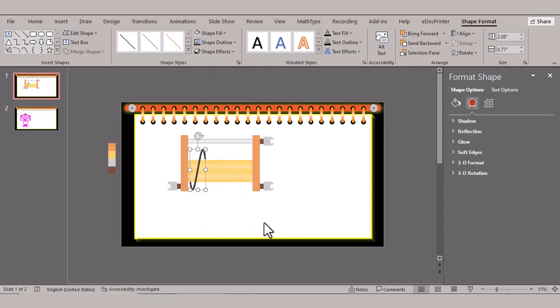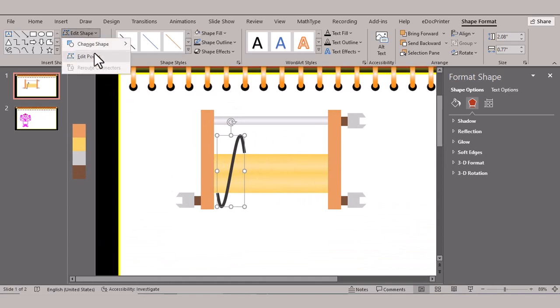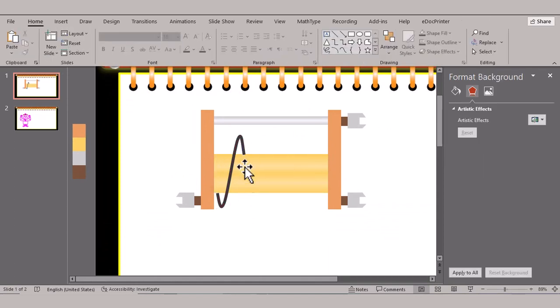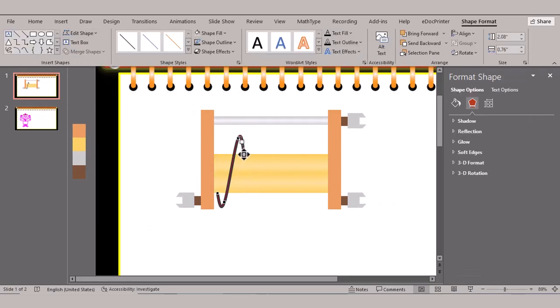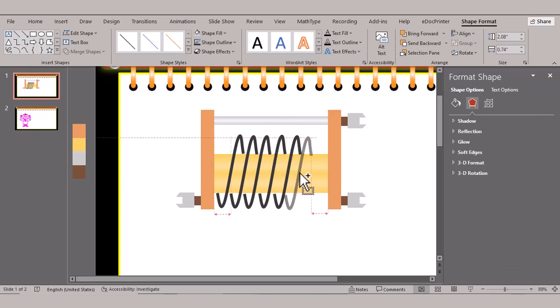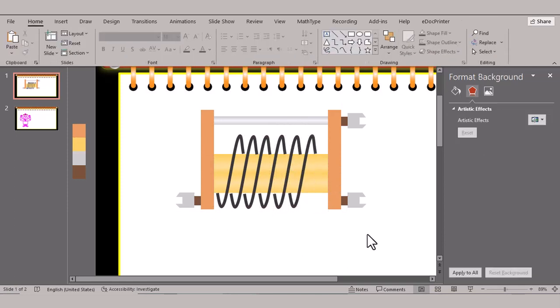As the rheostat is connected via one fixed terminal and one sliding contact, the active length between these two connections can be altered when the wiper is moved along a wire coil. The path taken by the electricity bridging these connections is therefore either elongated or shortened. In simple terms, this mechanical length adjustment is what creates variable resistance on the circuit, enabling the rheostat to alter and control current flow from A to B.